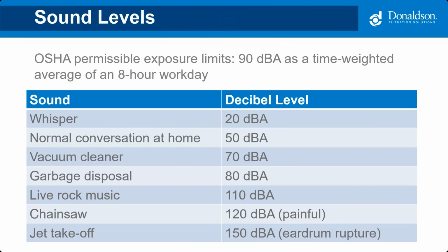But we should really talk about sound levels. Sound is an important consideration that not everybody thinks about when a system's being designed. Fans for dust collection systems can get pretty loud. And one of the reasons for that is the sound frequencies of fans are very similar to normal conversation. So even a fan that's well under an OSHA sound maximum sounds loud because you wind up yelling at each other to overcome the sound of the fan.